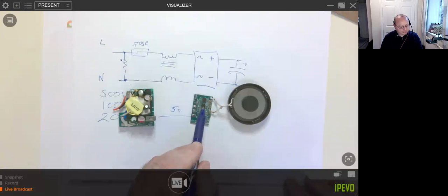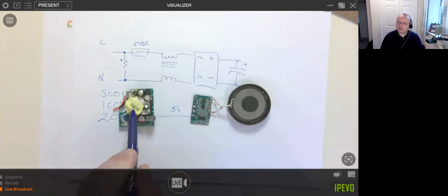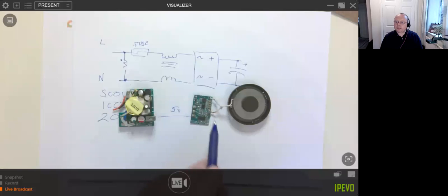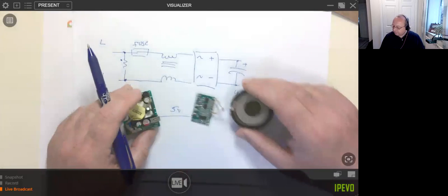So we've had to put a split choke. You've seen those blobs on USB cables. We've had to put one of those on, and it's only just saved the day with this power supply. So if I swap this power supply, it's got its own emissions, even though they both might have the correct stickers on them, it might push my radio emissions over the edge. So it's not all peaches and cream with this sort of stuff.